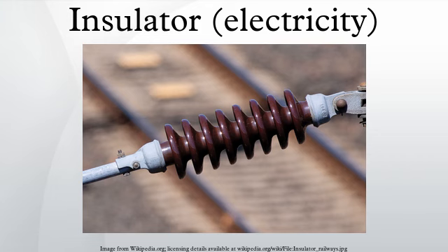To accomplish this, the surface is molded into a series of corrugations or concentric disc shapes. These usually include one or more sheds. Downward-facing cup-shaped surfaces that act as umbrellas to ensure that the part of the surface leakage path under the cup stays dry in wet weather. Minimum creepage distances are 20–25 mm per kilovolt, but must be increased in high pollution or airborne sea salt areas.